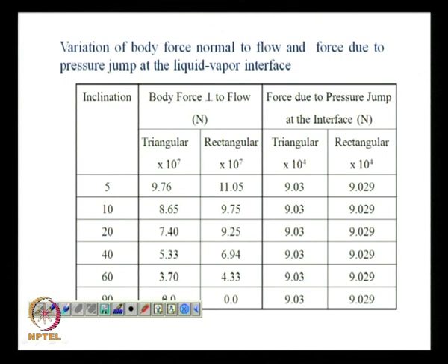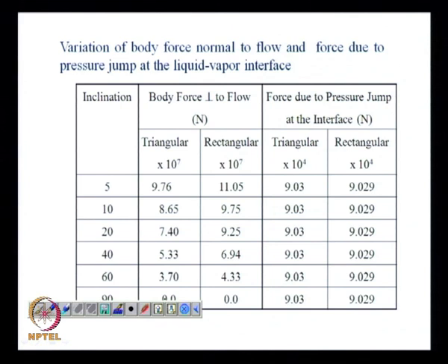And in the next slide we see how much the body force is with respect to the surface forces. We keep on saying in microscale devices that the body forces are rather unimportant; it is the surface forces which govern the flow. That fact is verified here by looking at the values of the body force and the values of the force due to the pressure jump at the interface, which can be evaluated by Young's equation, and there is an orders of magnitude difference between the two.